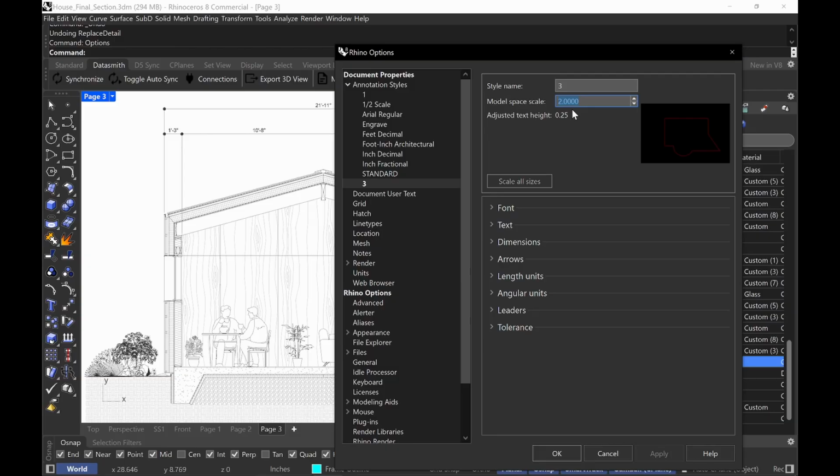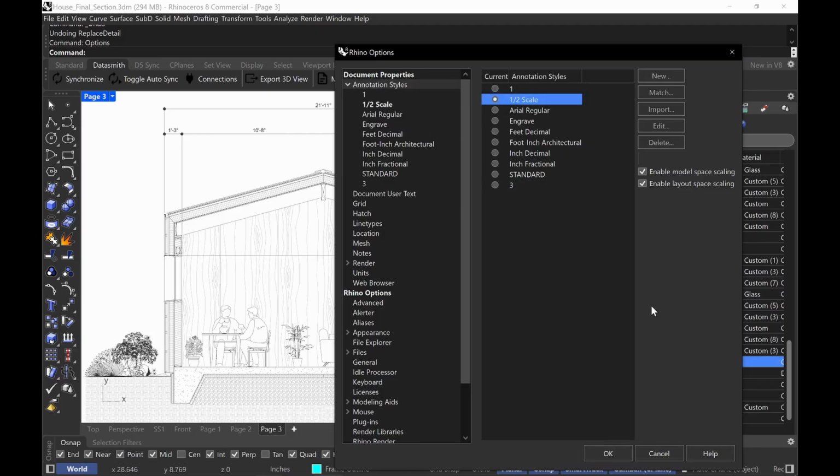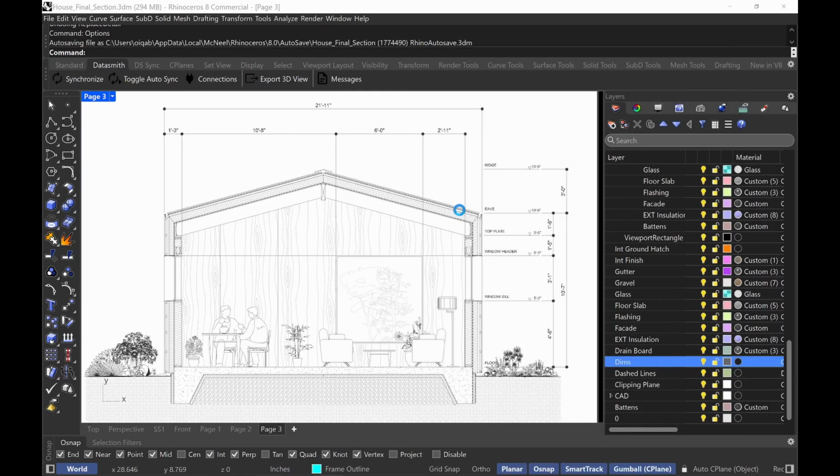You see, it's just going to start becoming smaller and smaller when you have a bigger and bigger scale. The text is going to get tinier and tinier because you're going to be more zoomed in, and the dots are going to be smaller. Everything's going to adjust. So I have one at 1 inch scale, 1/2 inch scale, 3 inch scale, right? If I do 0.25, apply. But I want to make sure this is actually okay for half inch scale.